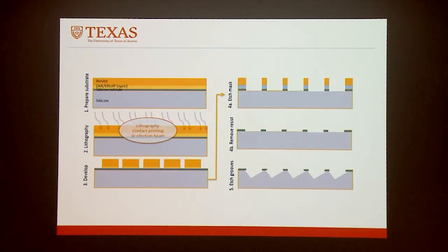So we go through a series of steps, and this is very much the way manufacturing is done for microelectronics, or was done 25 or 30 years ago. We use what's called contact lithography for most of it. We do some electron beam lithography to pattern a series of stripes, and then we sequentially remove different layers, trying very carefully to keep the precision exactly right of where the stripes go. They have to be positioned to about 20 nanometers over about 20 centimeters.